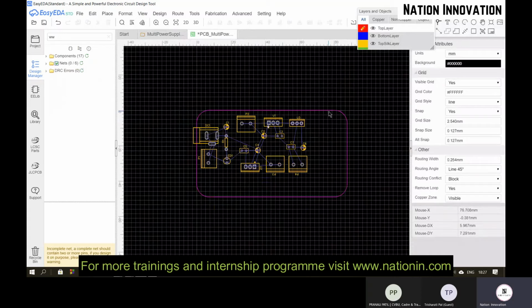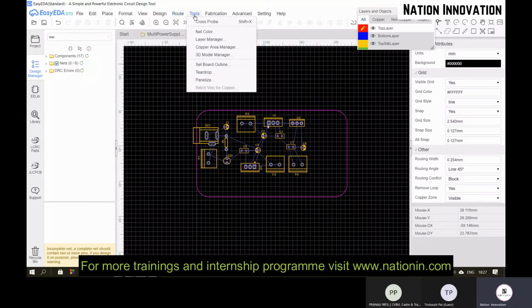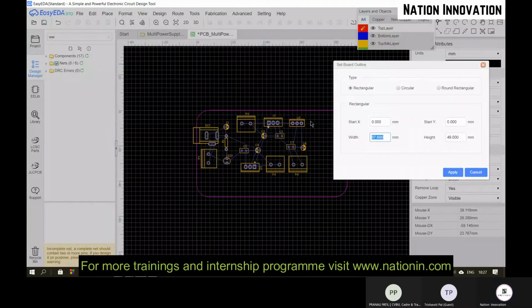So I am left with some space. I can change its layout border by going to the tools and going to set border outline. I can reduce its width and height. You can see that the width has to be reduced. Like I will reduce by 10, make it as 77, and height as 45.